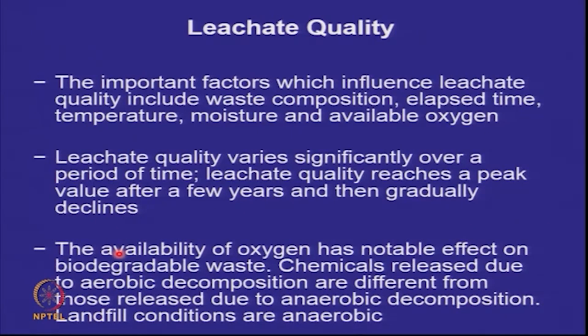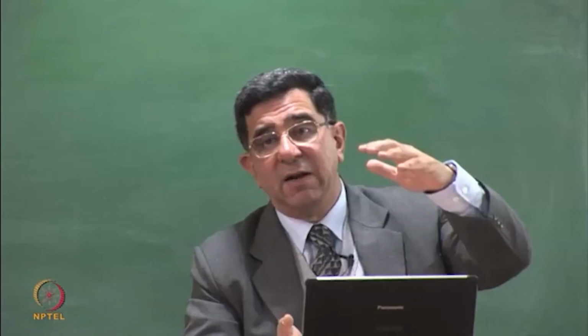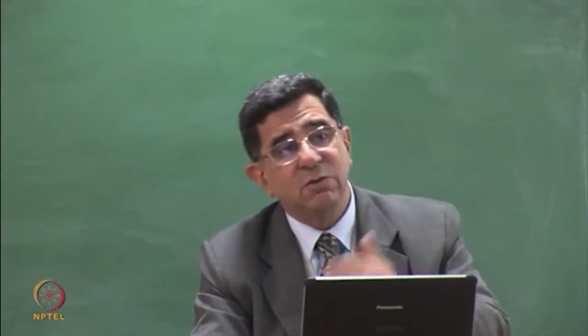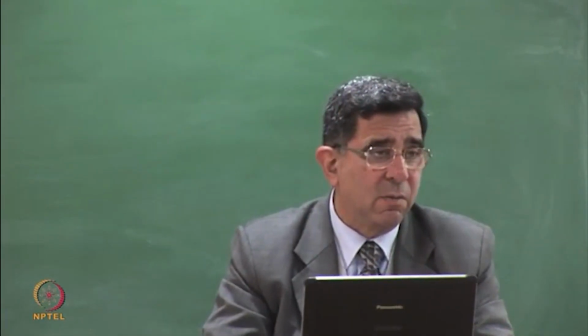In biodegradable waste, in municipal solid waste, availability of oxygen has a huge effect, whether the reactions taking place inside the waste mass are in aerobic or anaerobic conditions. Because the contaminants or chemicals released during aerobic decomposition are different from those released due to anaerobic decomposition. Landfill conditions are by and large anaerobic in the lower portion of the landfill, but when you are depositing fresh waste, there is oxygen in it. So they gradually change from aerobic to anaerobic.